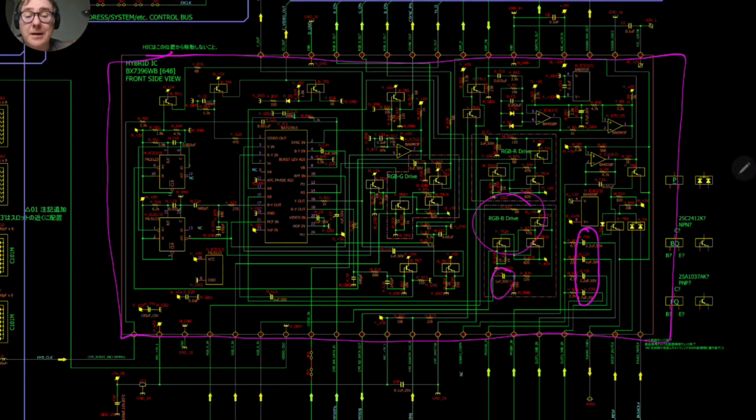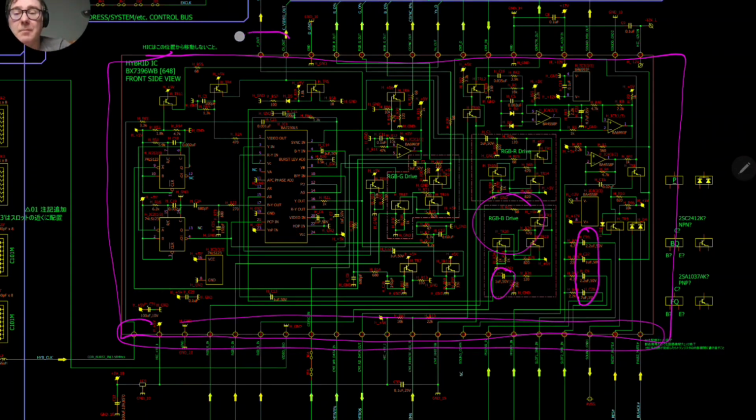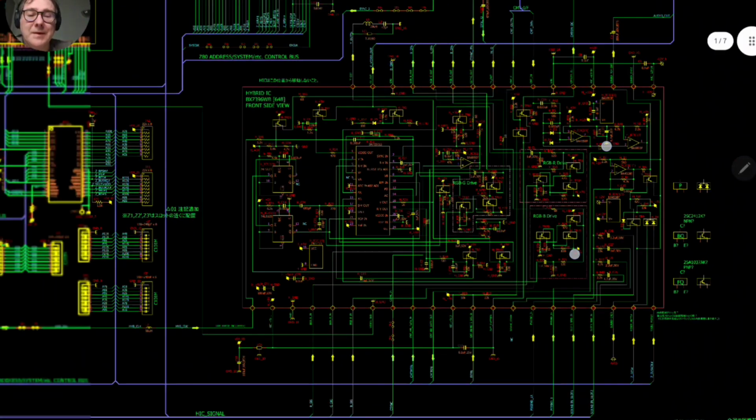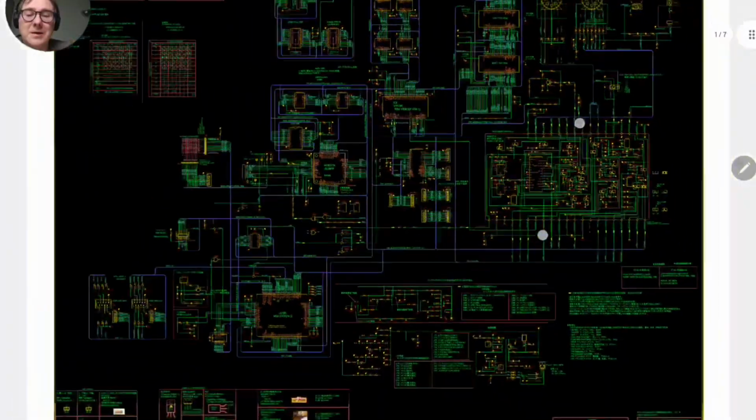I should, but if I want to remove or change these capacitors, I need to desolder this board, which is not complicated. The current which goes in here is low. This is just to generate the video output. So these capacitors were not under a lot of stress. So I think it should be fine if we don't replace them. I don't think I will replace the capacitors in here, but I will replace every other capacitor.